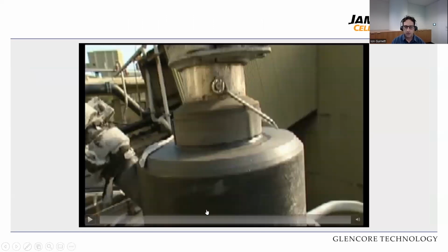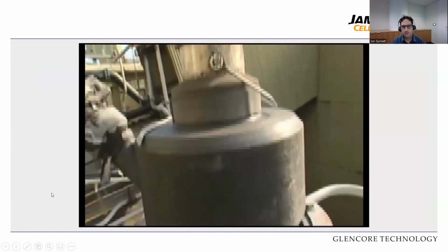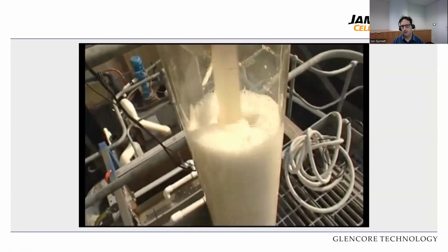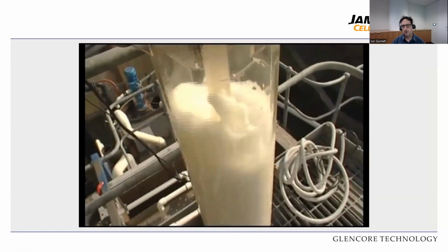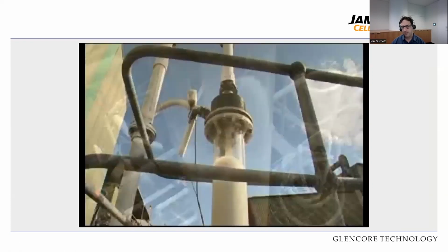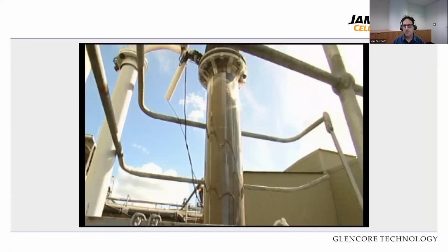Now, this is a video of a coal cell with a poly downcomer, but I feel it's really good because it actually shows you what's happening in these downcomers, and this scales up all the way to the full scale installations. As you can see, it's very turbulent, very intense mixing, and that's what makes sure that you get that particle bubble contact. The position where the slurry and mixing zone happens is a function of how much air you're letting in. Since this is close to the top, we're limiting the amount of air we're adding. If you want to move that further down, you add more air.